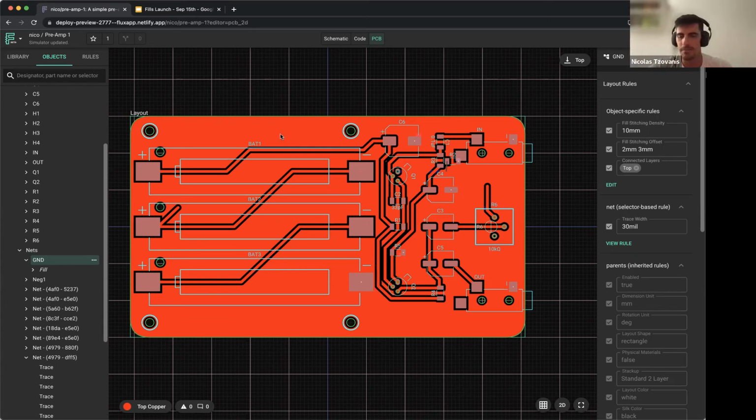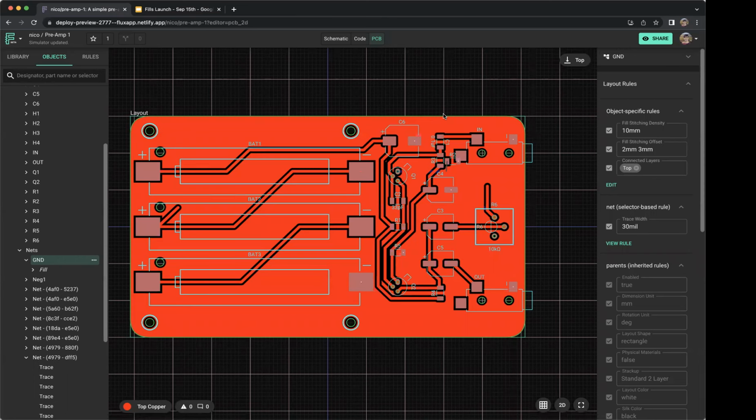Yeah, a good example is when you put a module that has an antenna on it. The antenna cannot have ground or copper below or above where the antenna is placed most of the time. So in that case, as Bruce was saying, the component has a specific requirement. So in the component, you will set up the keepout, which is intent-based. You're actively saying this component needs to have a keepout in this place. That makes sense. And that translates everywhere. Yeah, antenna was perfect, because otherwise you absorb all your signal with all the ground around it. It's not an antenna anymore.